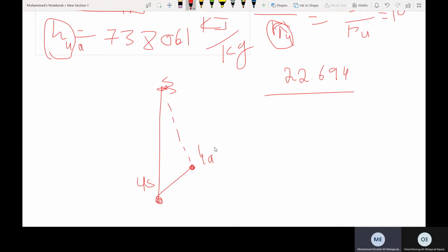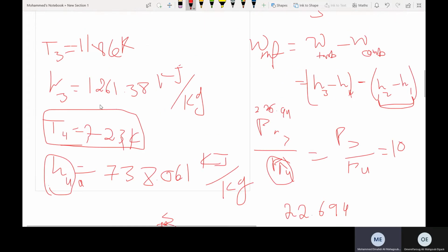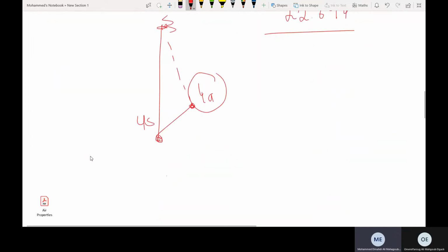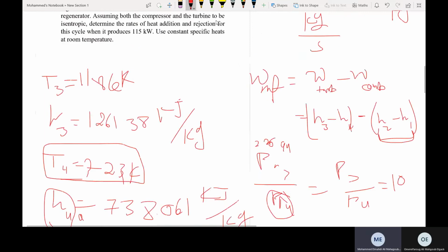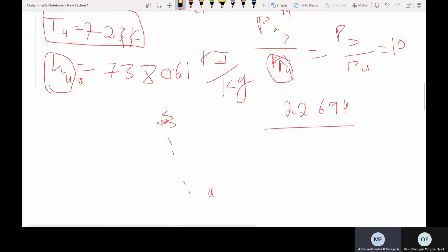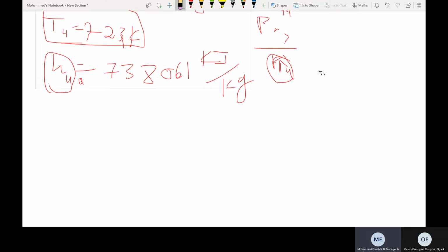So this makes sense, and this tells us that whenever we have the temperatures of both points, then that point is going to be the actual, because we don't need to do the isentropic thing and then divide and then get the pressure relative and then go. Okay, so remember this. You can say as if the information given in the question that the turbine has an isentropic efficiency of 88% is irrelevant for us. We will not use it because we have the temperature.